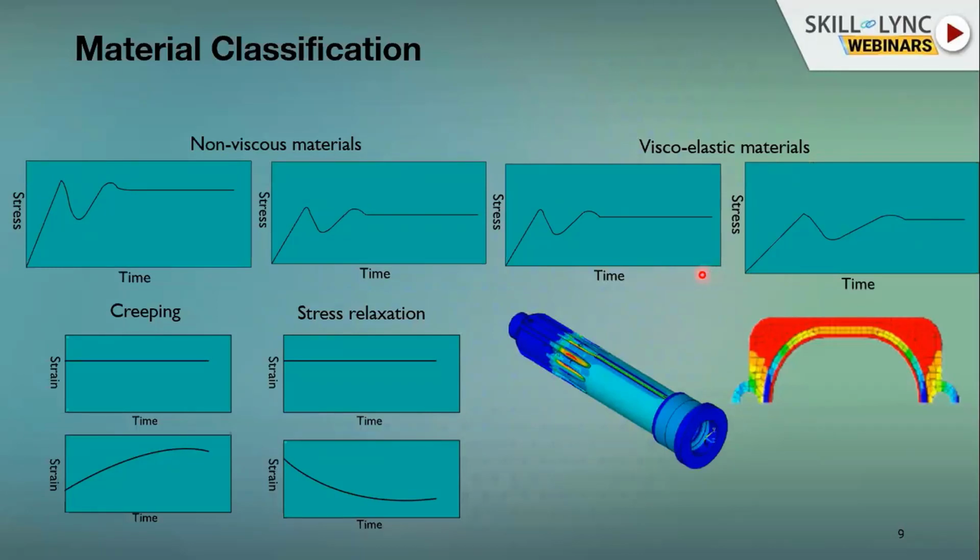You must not have observed it, but you can observe it moving forward. There is some kind of adhesive or material used on the floor of your car, probably in the boot space, where there would be certain shapes on that surface. All this is based on some kind of viscoelastic material fitted inside or onto the top of it, and then they would have another layer. This increases damping, which reduces the vibration, which in turn reduces the noise levels.